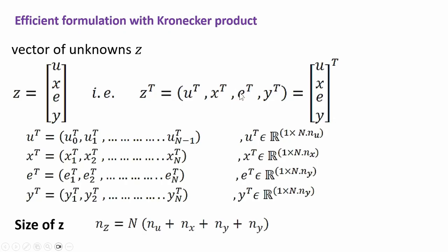And of course, for multiple input and multiple output, or MIMO, systems, you can control not only just one control input, but many control inputs. So u could in itself be a vector. Similarly, there can be more than one state in a process, so this x in itself can be a vector of more than one state. We could also control not only just one single output at a time, but more than one output simultaneously.